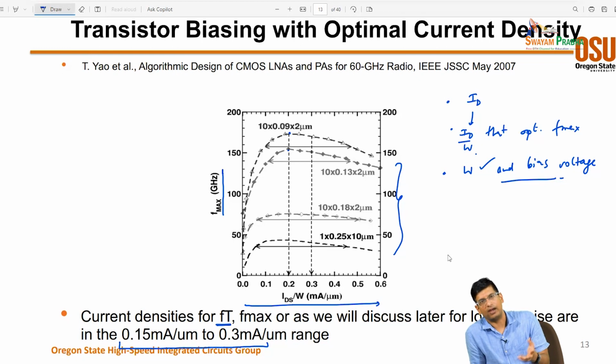From an amplifier perspective, there is a little bit of an iterative process within that. You do a layout, and then you find the maximum current density for that particular layout, and you find out what that Fmax is. You iterate a couple of times until you find a good Fmax and current density combination, and that becomes a unit cell that you use in your design.